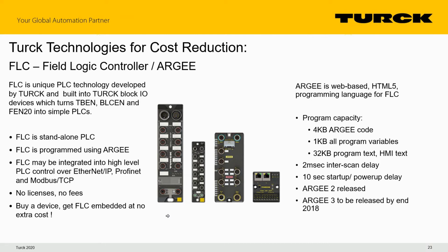And like any I/O system, you can tell the block that, on a communications loss, turn all the outputs off. But there's no staging to that. It's just when the block detects the communications loss, all the outputs go off instantly. If you've got pumps pumping and a valve immediately downstream, turning the pump off and closing the valve simultaneously is probably not good. So by adding FLC to it, we can now stage that shutdown.